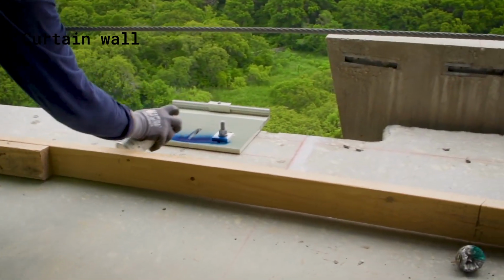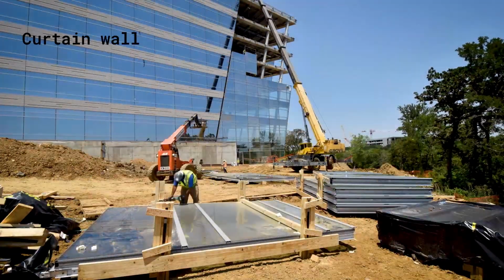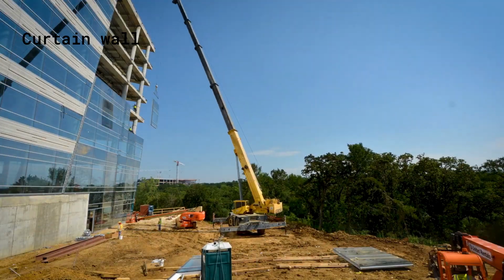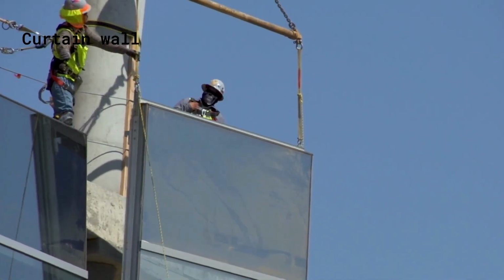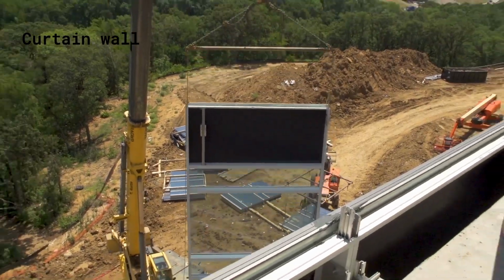Often the most difficult to detail, curtain walls are non-structural cladding systems for the external walls of a building. They're generally associated with large multi-story buildings, typically office space. Curtain walls only support their own weight and the loads imposed on them, such as wind loads and again seismic loads, which they transfer back to the primary structure of the building.